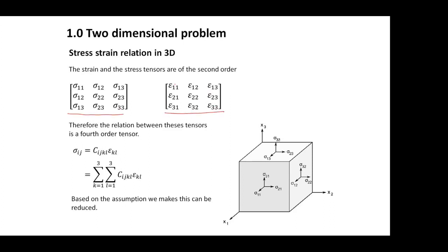But if you look into the stress in 3D, it actually consists of 9 independent components. I mean, it is a 3x3 matrix. Actually, it is a 3x3 tensor. But for the time being, let us call this a matrix. So it is a 3x3 matrix. And in the most general case, this is not a symmetric one.